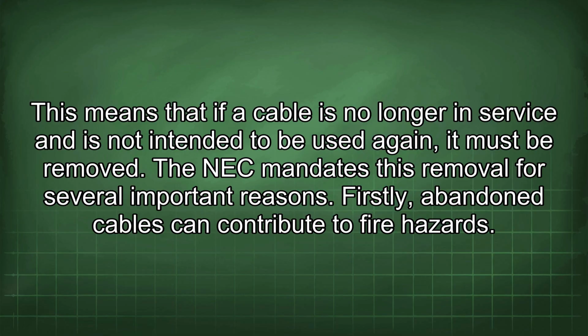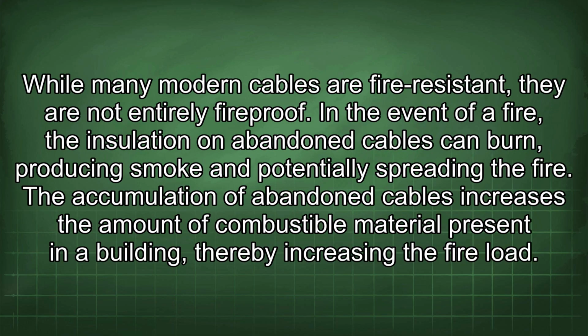Firstly, abandoned cables can contribute to fire hazards. While many modern cables are fire-resistant, they are not entirely fireproof. In the event of a fire, the insulation on abandoned cables can burn, producing smoke and potentially spreading the fire. The accumulation of abandoned cables increases the amount of combustible material present in a building, thereby increasing the fire load.